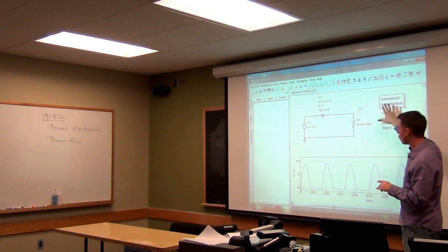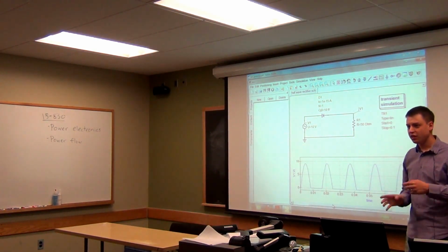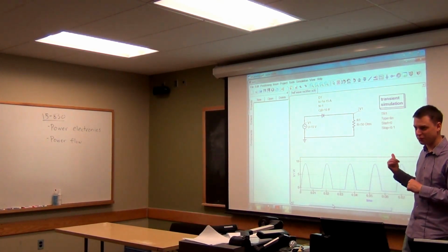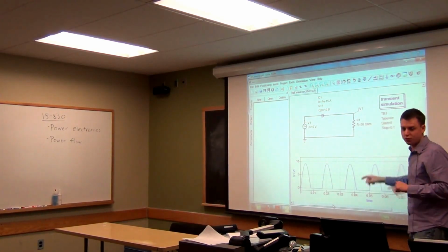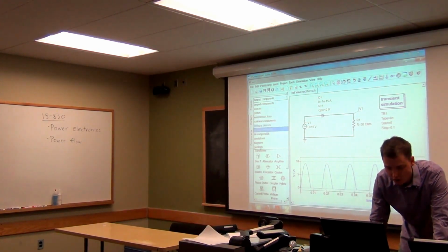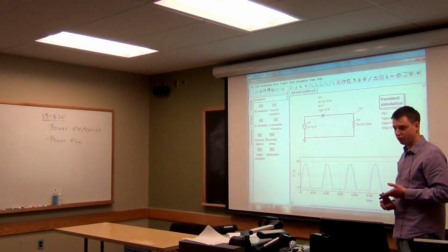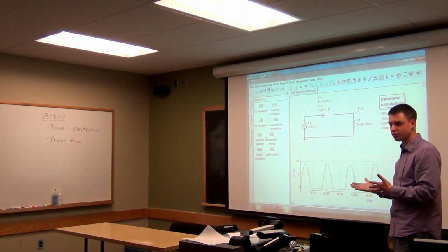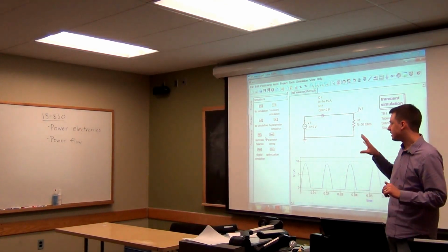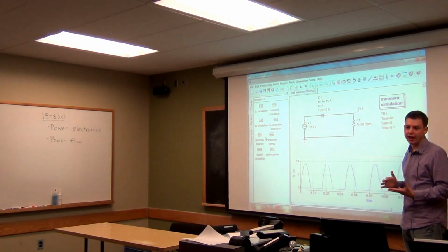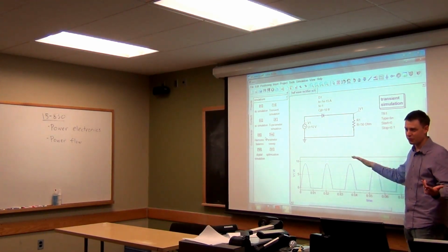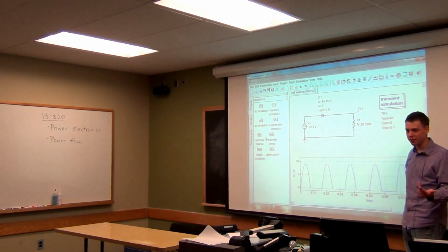But for simulating things like this, nonlinear circuit elements, we need one more type of simulation for our simulator Quux here. We need a transient simulation. So remember, in our set of components which we're going to look at for the homework, there are DC simulations, AC simulations, which we'll use primarily, but there's also the ability to run transient simulations, where you look at the actual waveforms that go in and out. And for a setting like this, where you have nonlinear elements, you really have to do that, because AC steady state doesn't really make sense when you're chopping up this waveform so that it is no longer a sine wave anymore.